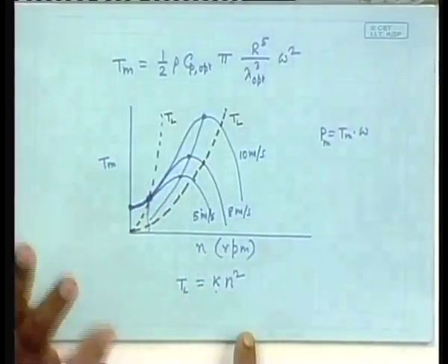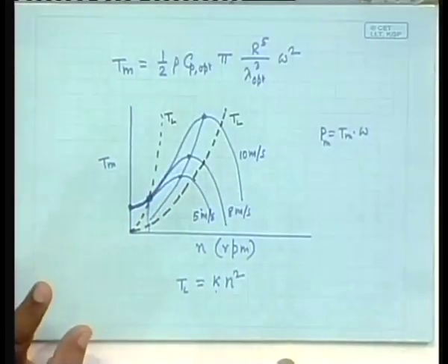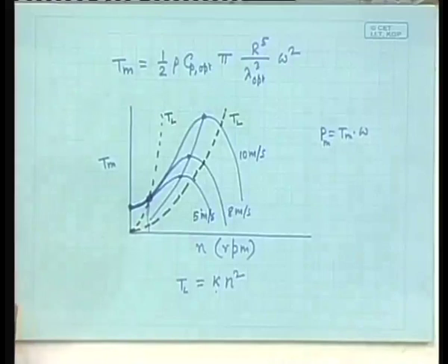The power is nothing but the speed of rotation times the torque. You are essentially controlling the torque. So, by controlling the amount of power that is fed from the generator to the load, you can tune it to operate on this line, and that is what is done, and that is what should be understood by the energy engineers. Clear?